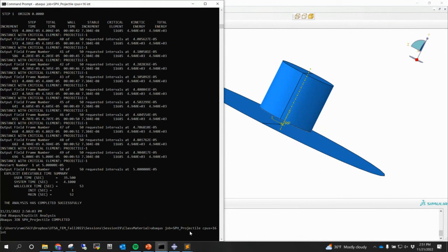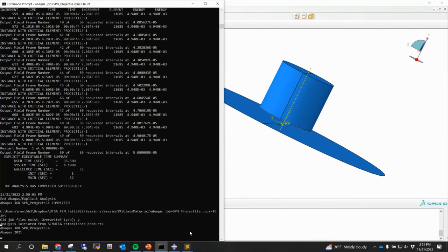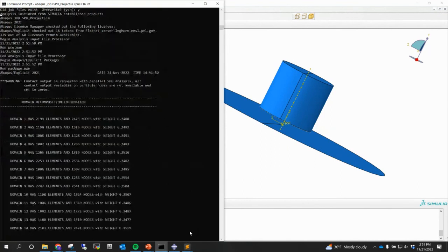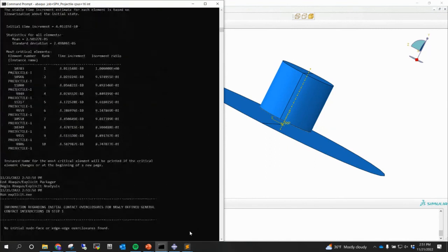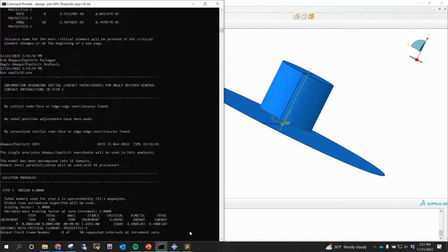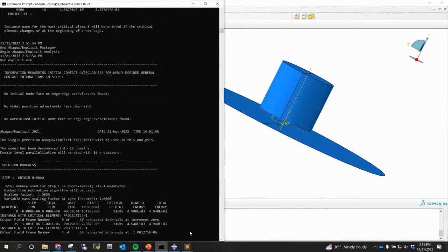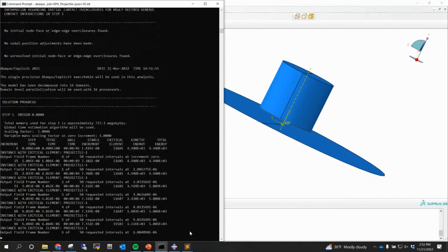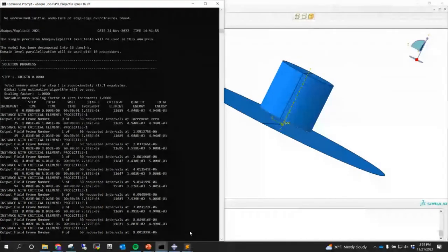Do you want contact there for sliding contact? Yes. And you can do viscous contact or static contact as well. So if you have something that is moving in a quasi-static way, so really slow, you have one type of friction. But if you have something that is moving at a really high speed, then you have a viscous or a dynamic friction coefficient.